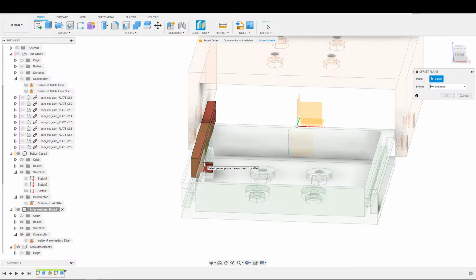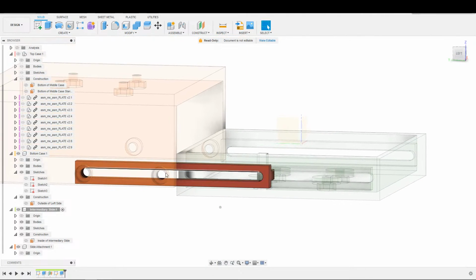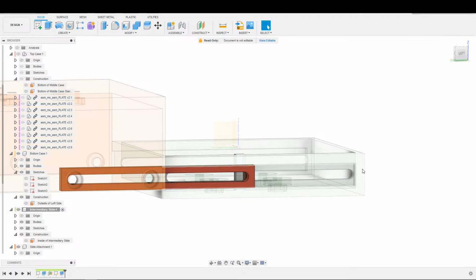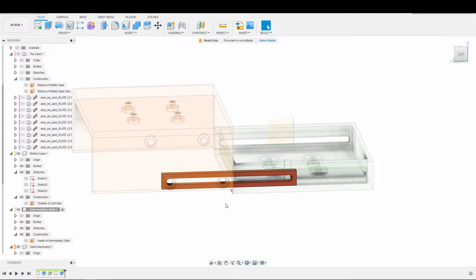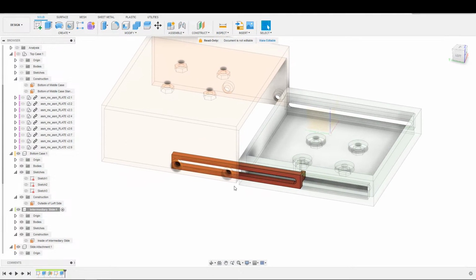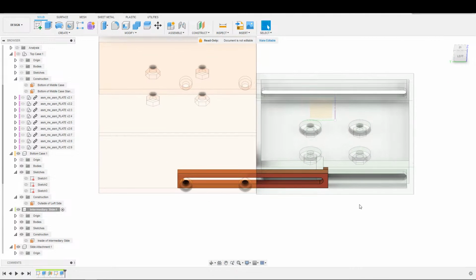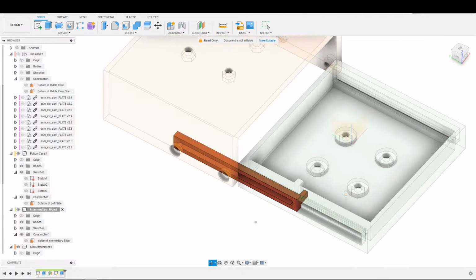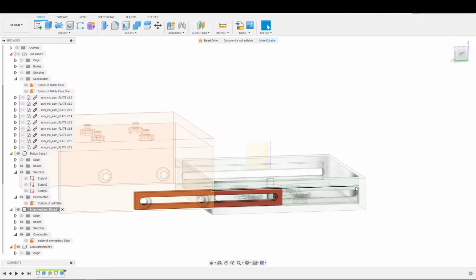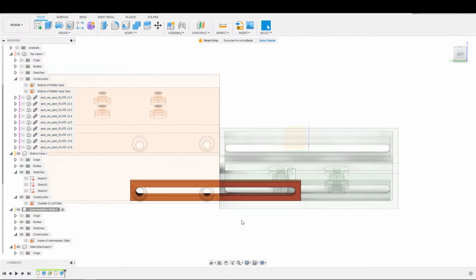Actually, I just realized we have a bigger issue on our hands. So the problem was these bolts coming forward, right? Those bolts are going to come all the way forward to the front here. So we can actually avoid this problem altogether by moving this second bolt further back. We won't be able to avoid this issue right here, but we can avoid the problem with this coming all the way to the front by moving it further back. And then we will come back and solve this issue. The reason this is a problem if this comes all the way to the front is that it actually can't get to the front because there's not enough meat because we offset this. I think, actually, I don't know that for 100% sure.